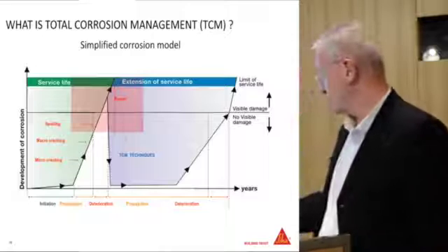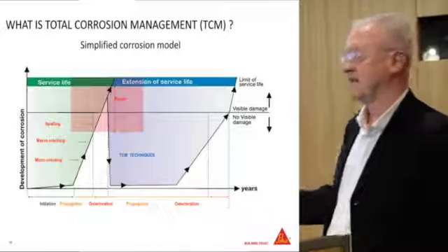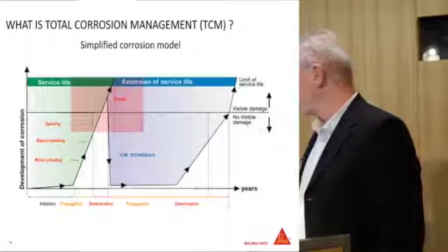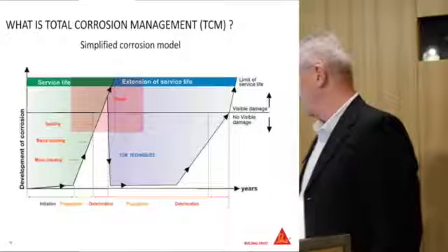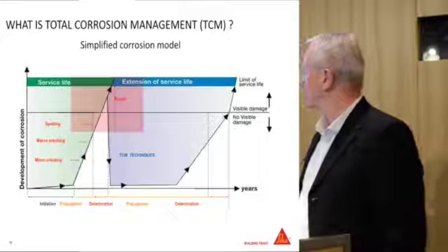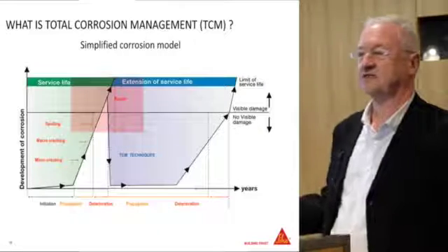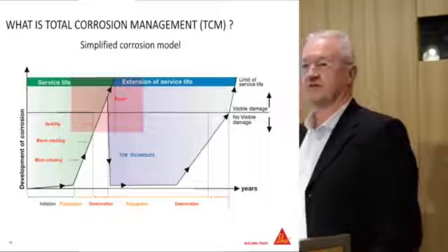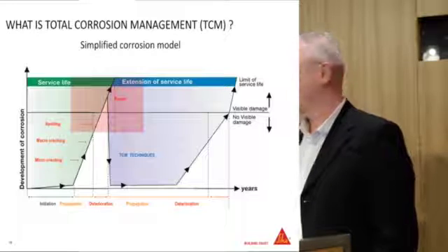So what we can do is control it, and depending on the system used and how long you want to extend the life for, we can apply the appropriate systems, and then as soon as they go beyond their service life, unless you reactivate them again, you're going to get a stage of deterioration, and we'll get back up here. And it could be that it's chosen that, yeah, we only want 50, 60 years out of the structure, so this ends up being 60 years. Whereas it could have been 15 or 20 years, or in the Middle East, as Chris showed, it was 3 or 5 years if you're not careful.